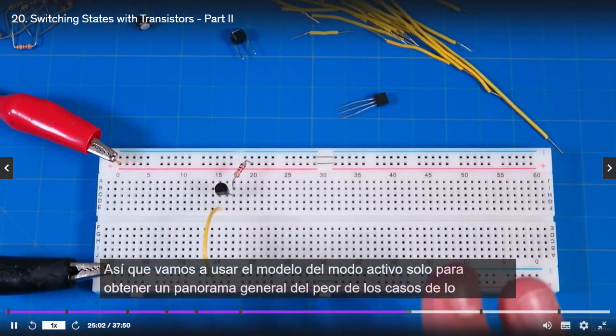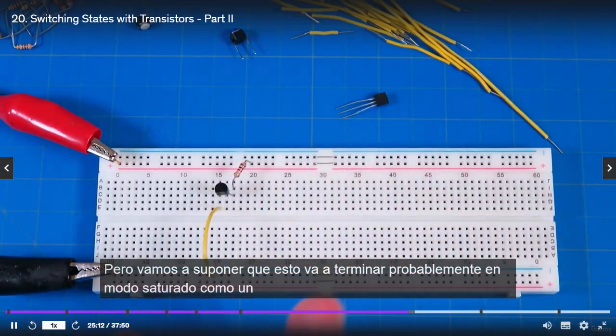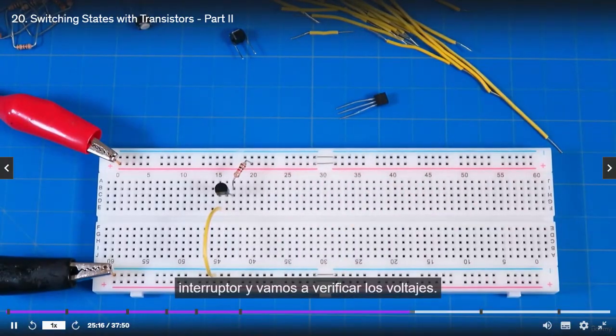So we're going to use the model of the active mode just to get a general worst case scenario of what's going to happen with the current, but we're going to just assume that this thing is going to end up probably in saturated mode like a switch, and we're going to check the voltages.